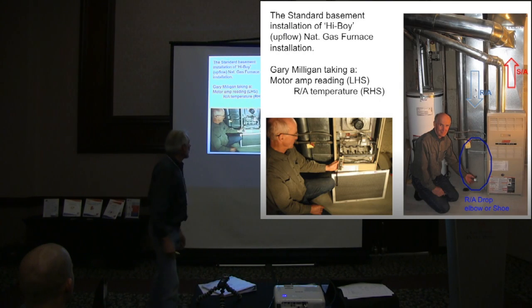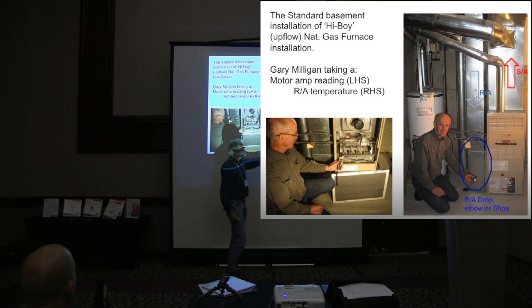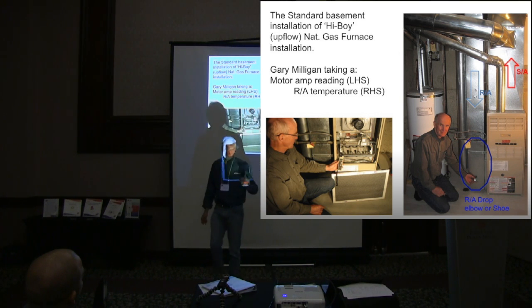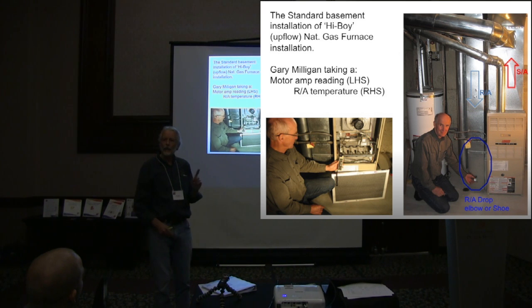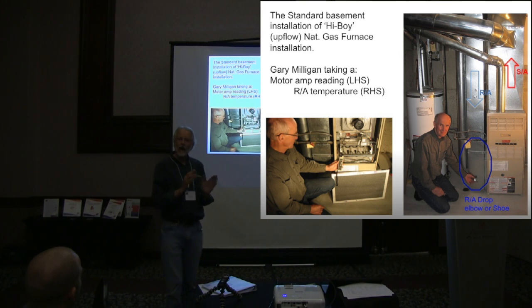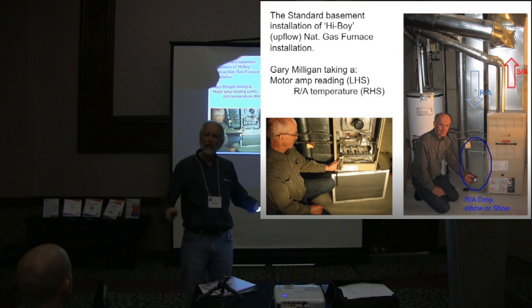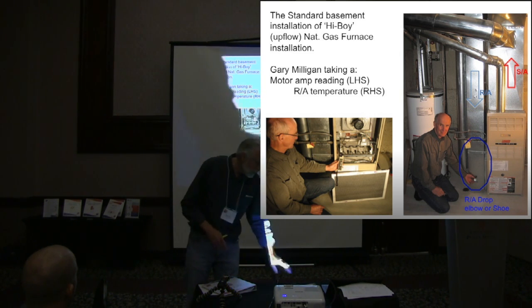And it's not very hard to get in there and actually measure. In this case, it's a temperature rise, but you can take static pressures and find out exactly what happens to each one of these fittings. In fact, with 10 minutes worth of work, you can determine exactly how good or how bad the ductwork system is without even seeing anything, if it's all behind gyprock. A couple of static pressure measurements will tell you exactly the adequacy or the total shortfall of duct systems in an existing home without even seeing one thing, without even looking how much plate's been cut out, which is the common culprit.